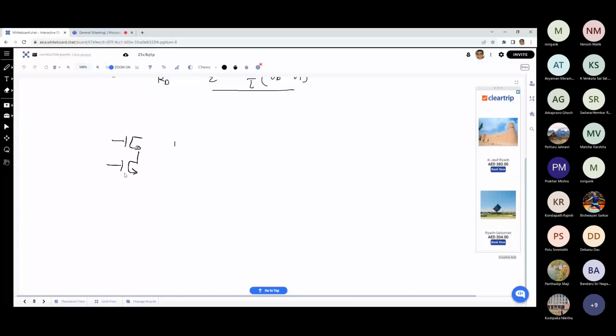So now I can definitely do this in the reference branch, whatever current is coming, and I can stack another transistor, get a VB over here, and then I can take my output current from here, Iout. In this case, my output impedance is gm RO square, right? Because looking into the drain of a stacked MOSFET, if you have two MOSFETs like this, you get gm RO square. So as compared to RO, the output impedance is boosted by gm RO, which is going to be a large number. Output impedance is going to be larger. This is going to act more like an ideal current source. The ideal behavior has increased, or it is coming closer to an ideal current source because output impedance has increased.